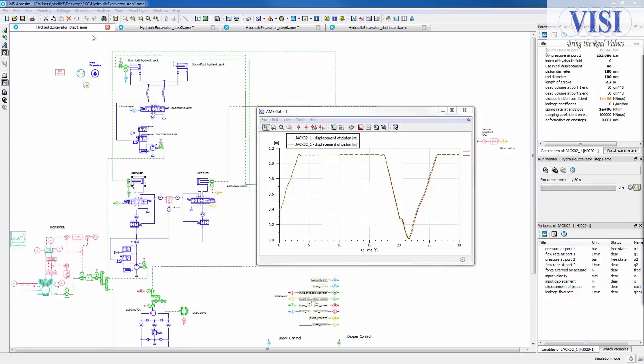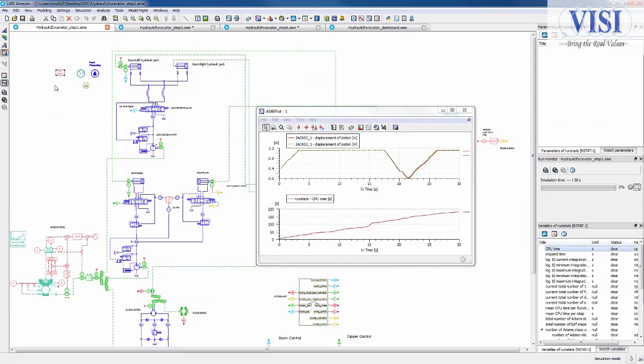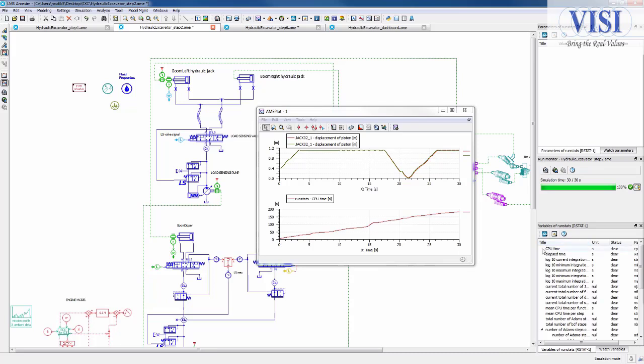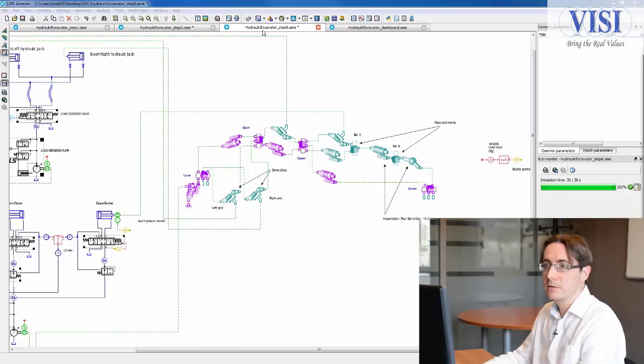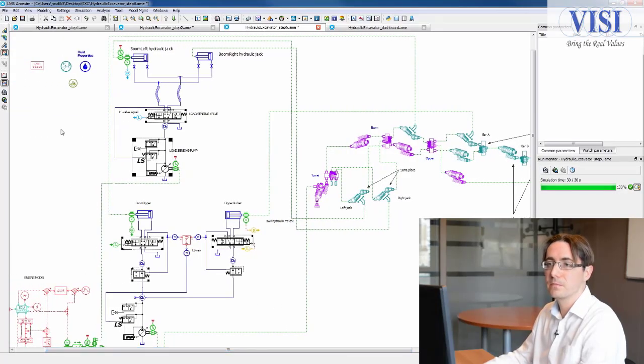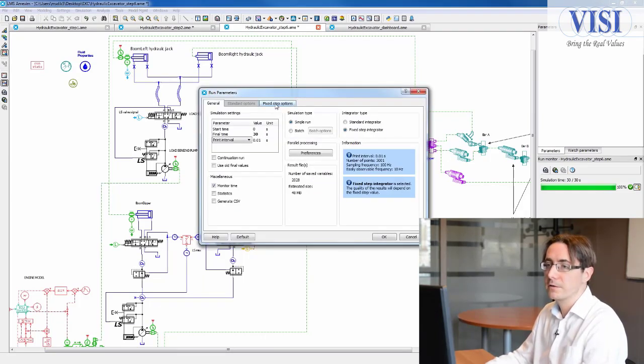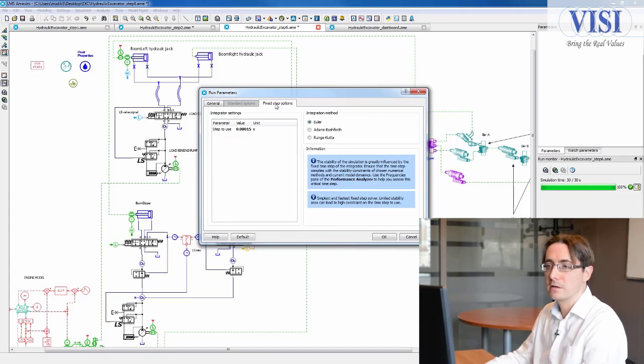But if we look in terms of CPU time, we will see that we have a huge benefit from the modification of the volume of the chambers, because here we have reduced the CPU time from 180 seconds to roughly 85 seconds. So we have divided the CPU time by more than 2. Step by step, we continue the analysis, still using the 2 different tools that I presented before, the performance analyzer and the model projection tool, and we can reach almost real time.